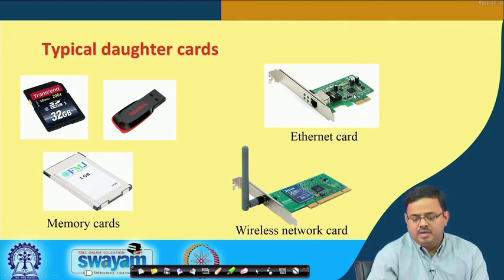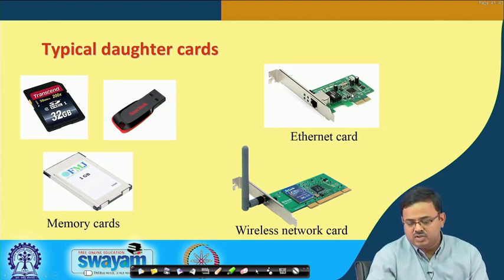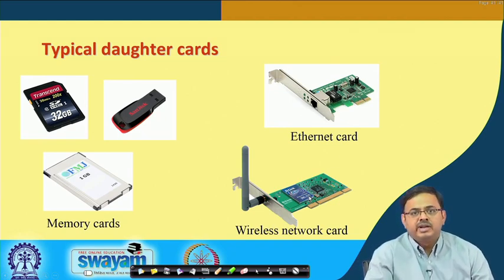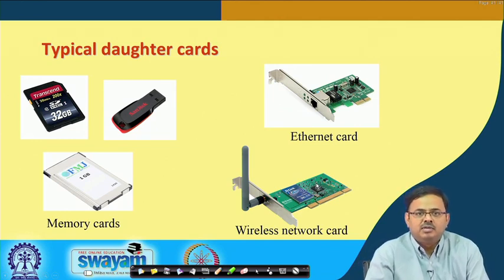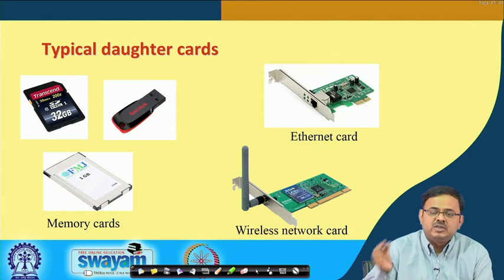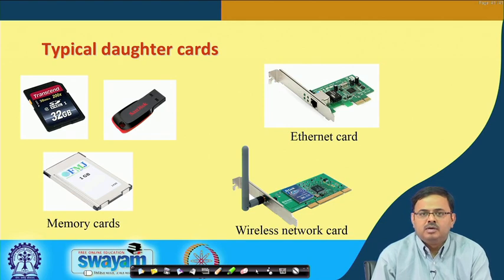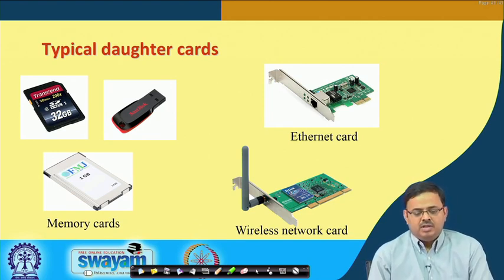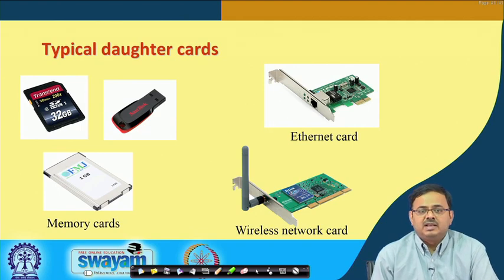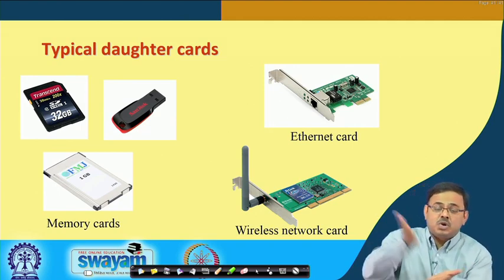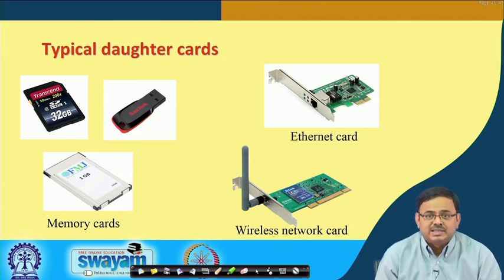Okay. Many of them are, as you can see, peripheral packages. I do not know how large it is on your screens, but you can see some of these can be even ball grid array packages, direct bonded. Probably in these smaller circuit cards, it is not very common to see the piece of silicon on its substrate, which eventually is connected on the motherboard. These are typically chip on board. Okay. So, these are typical daughter cards as we see, and these daughter cards go onto the motherboard, that is how I am slowly building up the system.